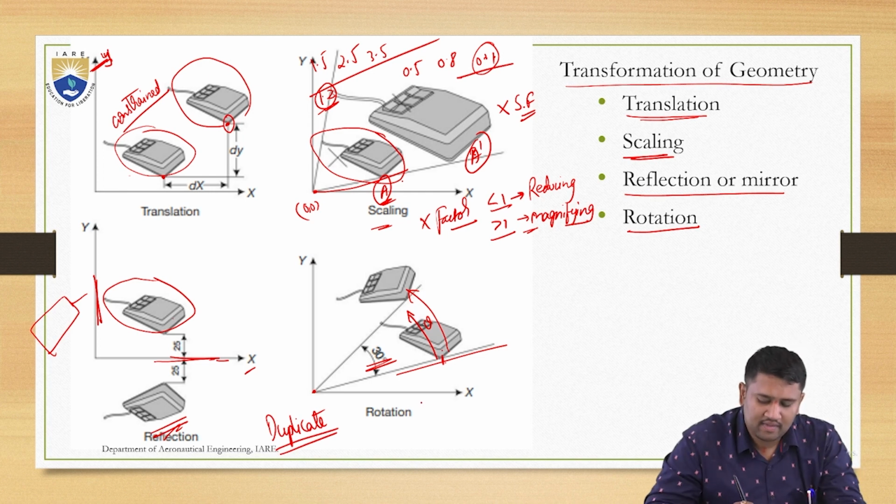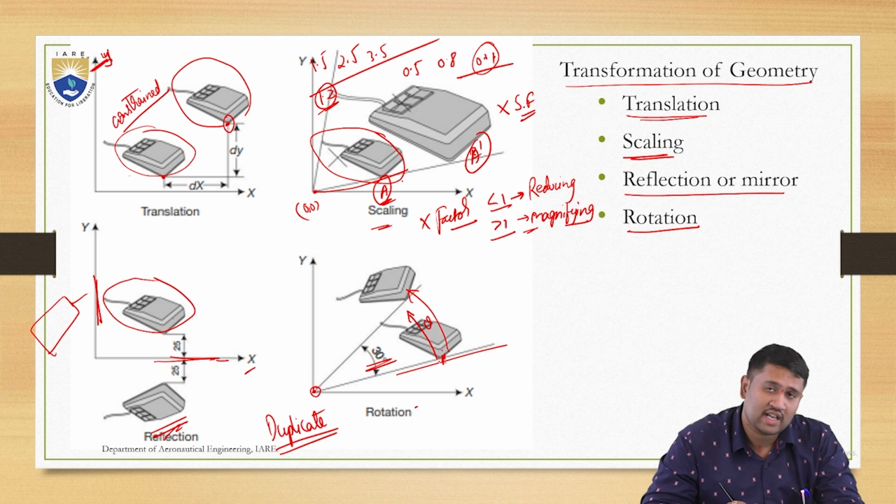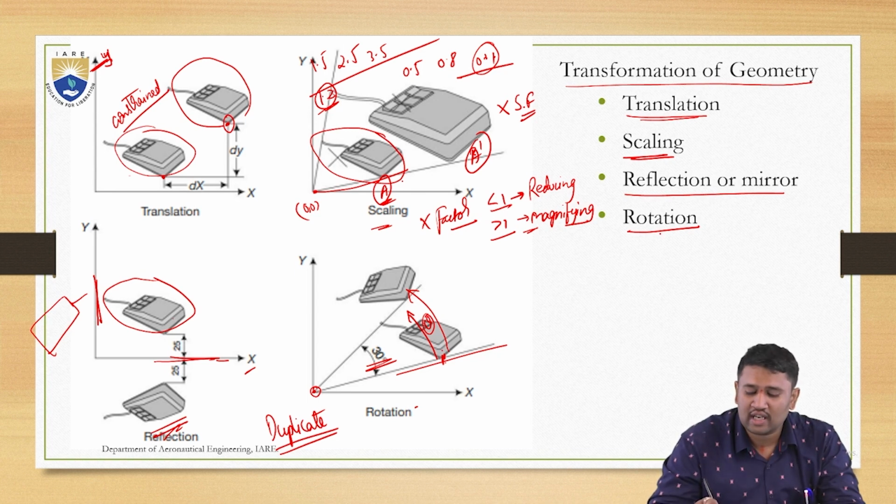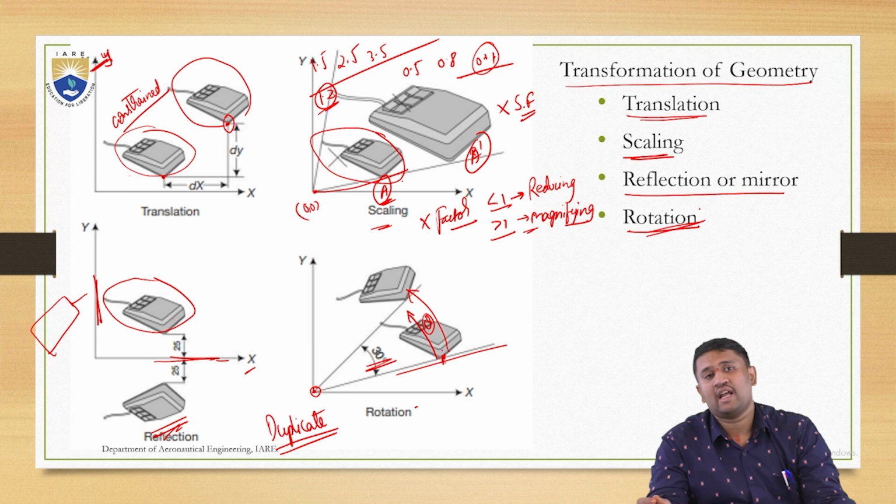Now, coming to rotation, you're supposed to select the center through which it is supposed to rotate, then a base point through which it's supposed to be lifted up, and the angle of your new inclination. On selection of all these three, you can clearly rotate an object.